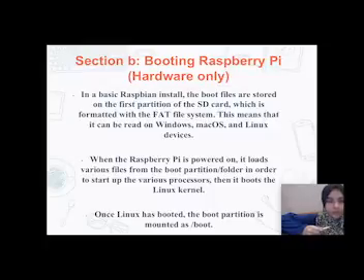In normal operations, the OS will be in charge and the GPU will drive the display, while in booting operations, it will play another role. So when the board is powered up, the booting begins and the GPU will turn on, while the ARM cores will remain off, and the GPU will then execute the first stage, reading the SD or micro SD card, and loads the bootcode.bin, which is the second stage bootloader, into the L2 cache.